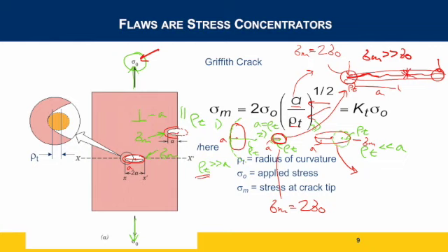Typically they'll do this for a crack that's small, right? When you first hit the windshield, they'll drill the whole crack, and then they'll fill it with the polymer material. And that reduces the stress substantially, but it's still twice the stress locally than the rest of the windshield, so that could be an issue. So a lot of times just replacing the whole windshield is a better way to go.